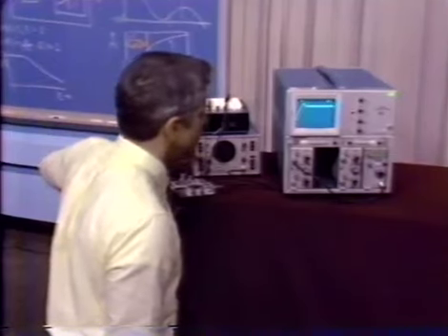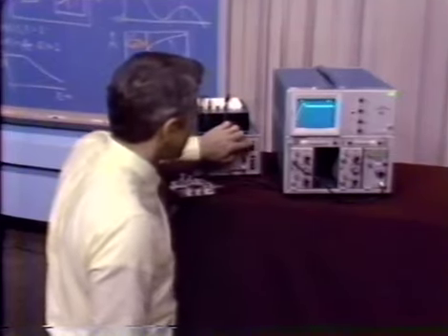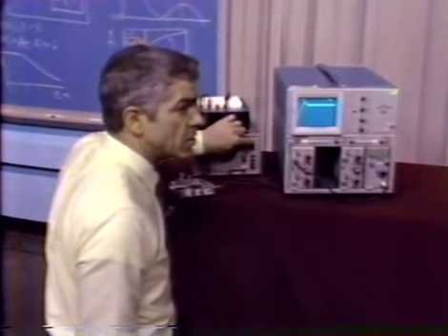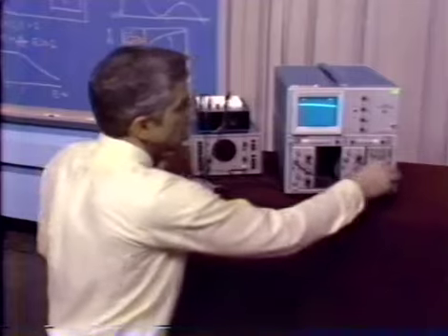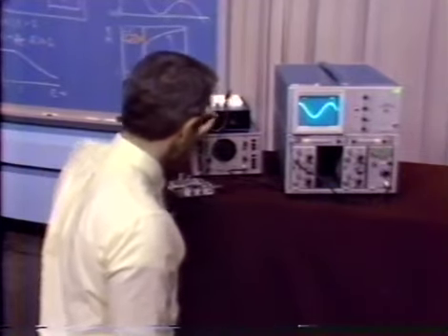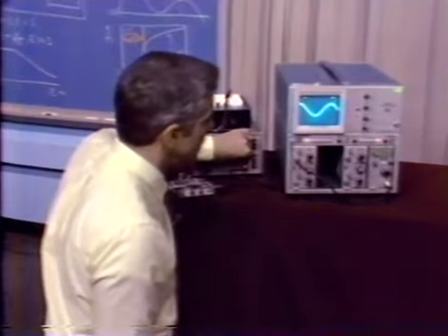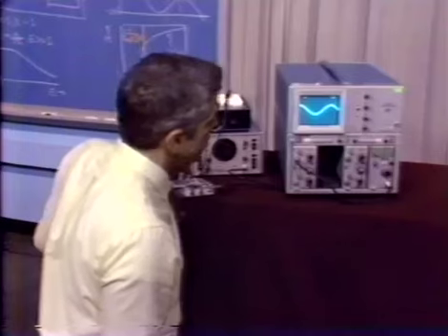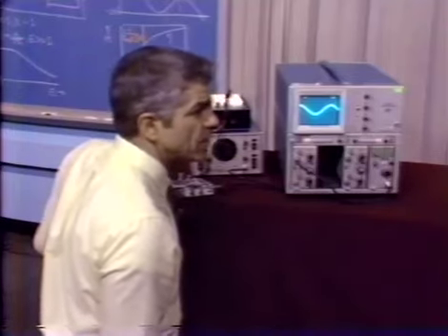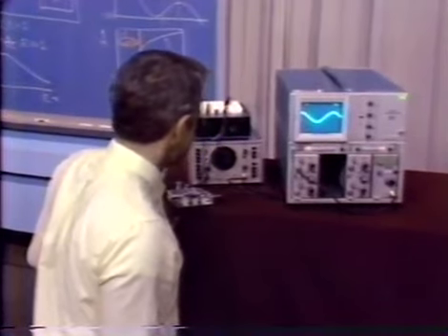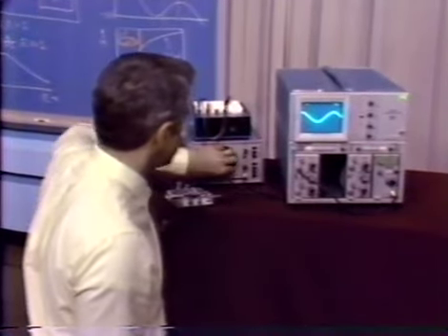Let's go to a somewhat lower frequency, and rather than use a square wave, which of course forces us into slew rate limiting on the transitions, let's look at the sinusoidal behavior. Let me just lower the amplitude a little bit. And here we're running at a frequency that's low enough. Let's say we're at 50 microseconds per division, so that's a couple of kilohertz. And that's low enough so that we're not slew rate limiting.